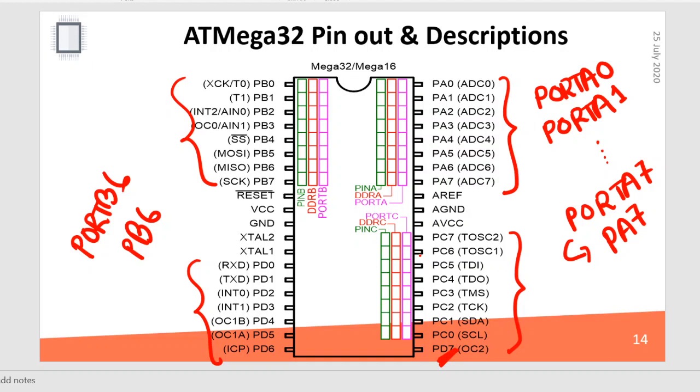So in an input mode, the port or pin is getting instruction from a peripheral device, and then it is passing the instruction or passing the data to your code. So in this case, it is working as an input pin or input port. So you can declare any port, any pin as input or output, but this declaration is for only one time. So you cannot use a port or a pin as input and output at the same time.